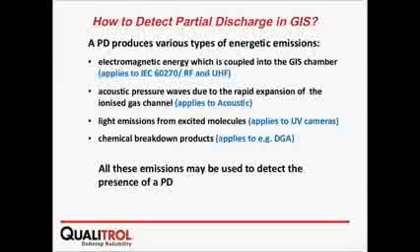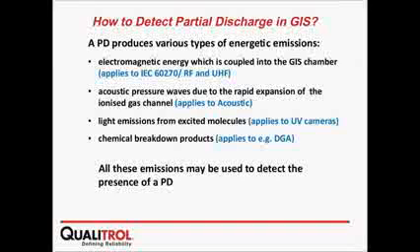And in the case of the GIS, you have the SO2. Since SF6 is part of the GIS and the high voltage breakers, and it is really good to distinguish the arc, any molecular system not able to recombine as SF6 again can become SF4. SF4 is a very reactive gas, so it will react with the closest component that is in there.